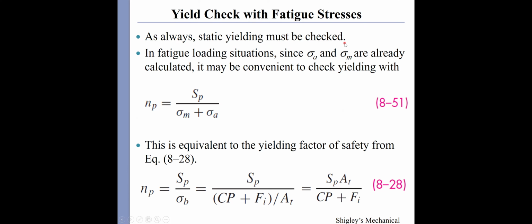Even if the case is fatigue loading, we still have to check static yielding: whether the static force will cause yielding. If the stress already causes the bolt to yield, we don't have to take any fatigue criteria into account, because static loading can induce plastic deformation.